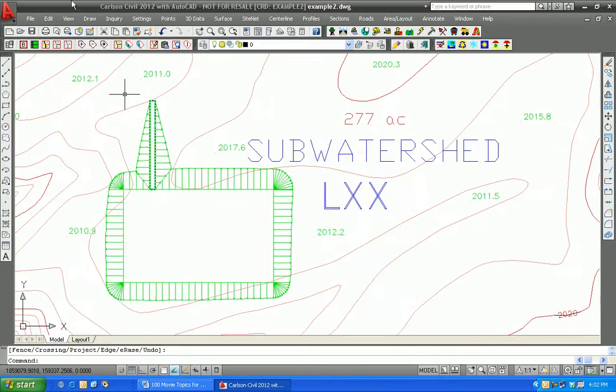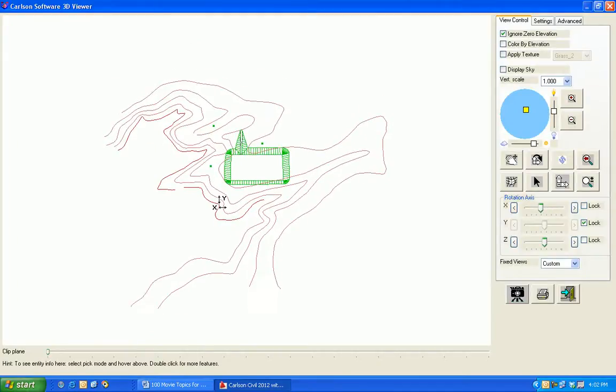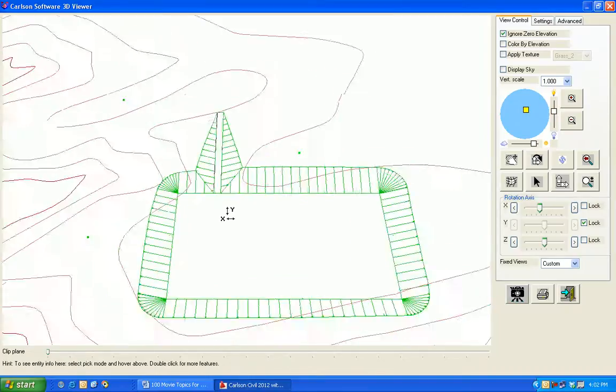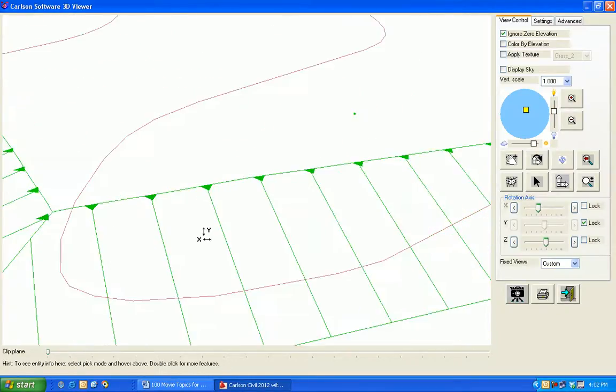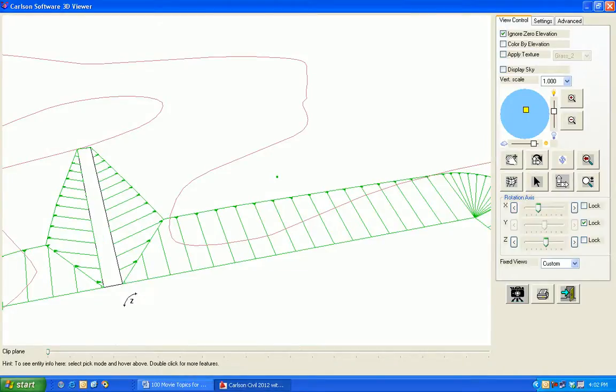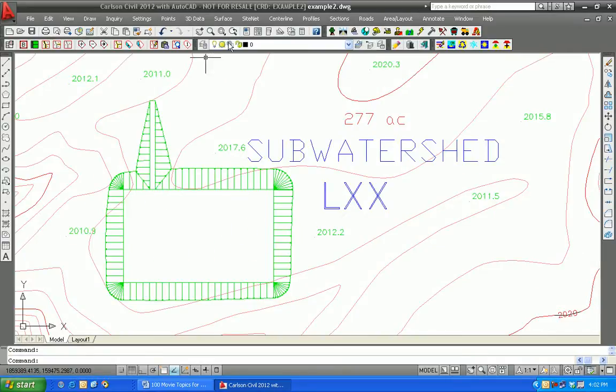Let's view this in 3D and see if we can clearly see the ramp entering this pit. And yes, it's very clear. Goes into the pit. Slope direction arrows help in the visualization of this process. And you even get the precise calculation of an interesting edge where one design contacts another, and that could be staked in the field. And you can create points using Draw Locate Points.